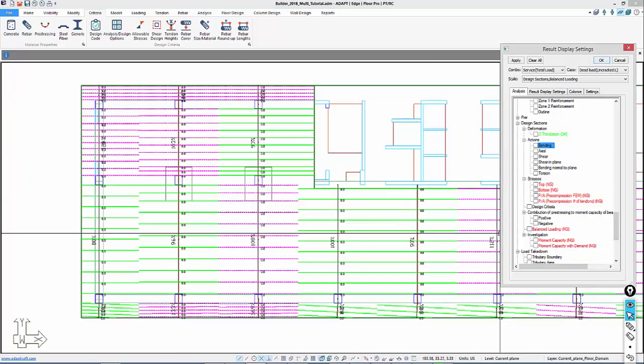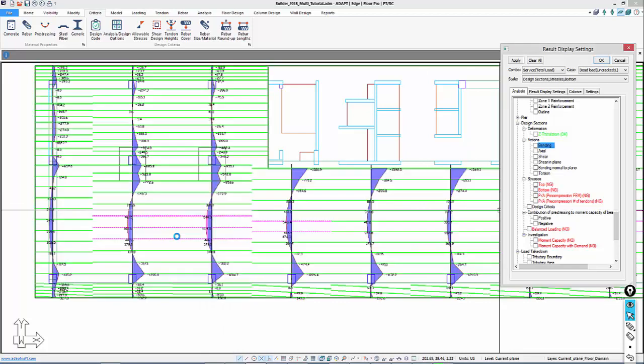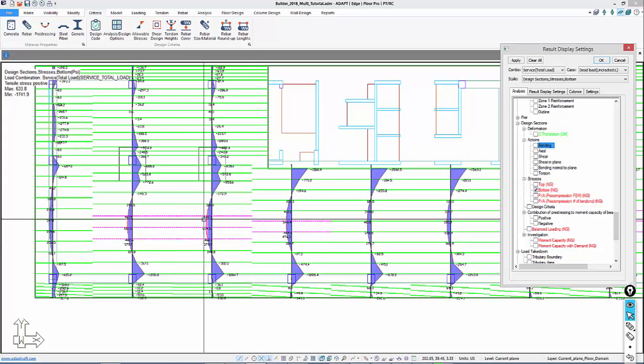Going back to balancing, we do have an overbalance here, but we also have a situation where we have too much tensile stress. So we can't move the cable up to compensate for balancing, otherwise our stress would increase. This is a case where the outcome of the design might be such that the load balancing maximum value that we've targeted is exceeded.